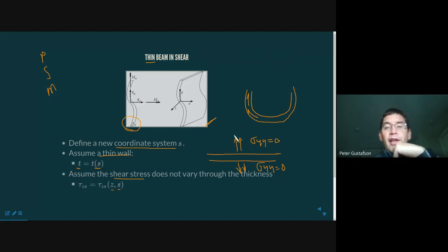Okay, the other thing to keep in mind is the governing differential equations for stress. Let me see if I can write them for you here. In fact, here I got my chalkboard back. So if you remember, I had sigma xx comma x plus sigma xy comma y plus sigma xz comma z was equal to 0.